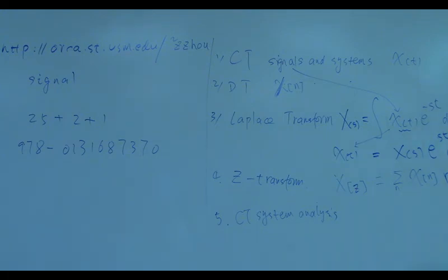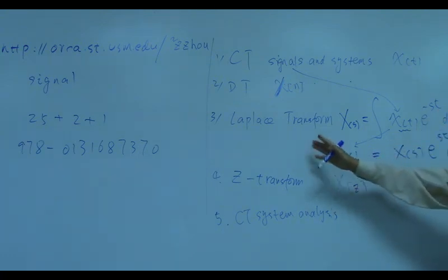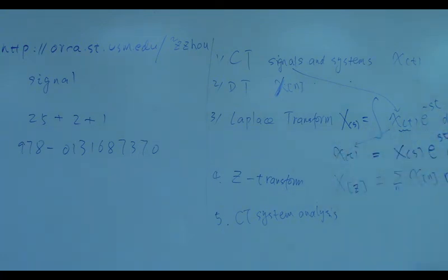So we get Y(s), the Laplace transform of the Y signal, the output. Once we get this, then we take the inverse Laplace transform, and we get the original output. So we take an extra step here, extra step here. In the first chapter, we know the signals, continuous signals X, Y, and we know the continuous system. And in the third chapter, we know the techniques for Laplace transform to convert x(t) into X(s), and the inverse Laplace transform to convert Y(s) into y(t), and in this one here, this is transform analysis to analyze this. So that is chapter 5.